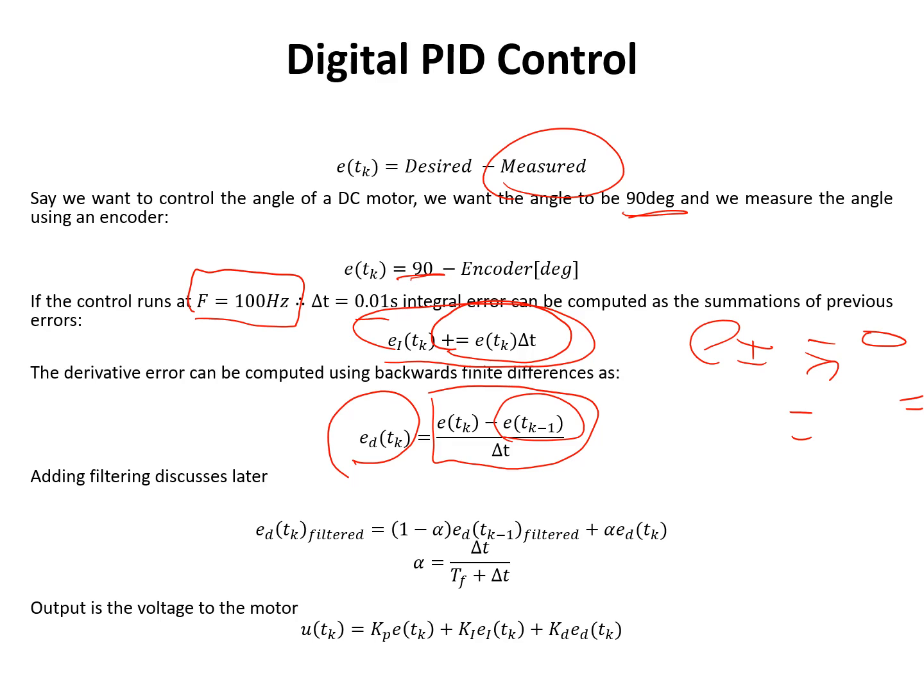Now, important to note, and we'll discuss this a little bit later, the problem with adding derivative control to your system is that in a simulation environment, you'll typically always have very clean signals unless you add artificial noise to your system. In general, simulations are perfect. There's no noise. Everything is clean. So the derivative is typically going to be very smooth and continuous.